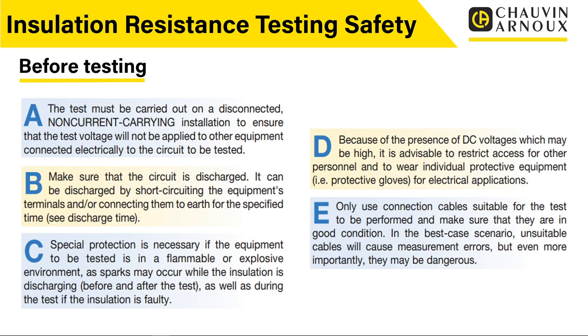D, because of the presence of DC voltages, which may be high, it's advisable to restrict access for other personnel and to wear individual protective equipment, i.e. protective gloves, for electrical applications. So yeah, just think about your PPE in this case. You'll often see in many pictures of people carrying out these types of tests that they are wearing insulating rubber gloves.